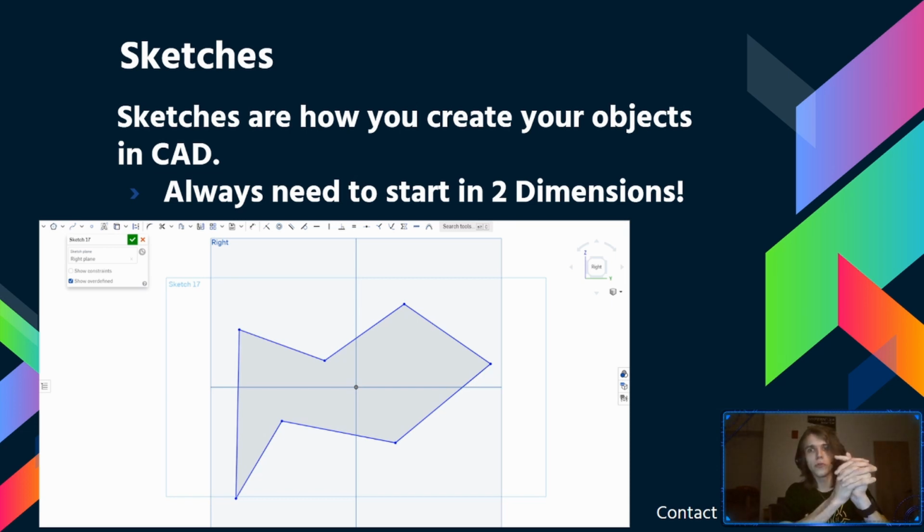There's a few things that you have to understand about CAD programs, but they all revolve around a few key features. And we'll be going over some of them here. One of the most important features of any CAD program is understanding how to use Sketch. If you think about it, in a CAD program, you're trying to make a 3D object, but your computer screen is a two-dimensional surface. So how do you make a three-dimensional object on a two-dimensional surface? And we do that in a two-step process that always starts with a sketch.